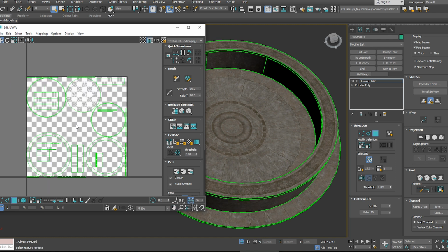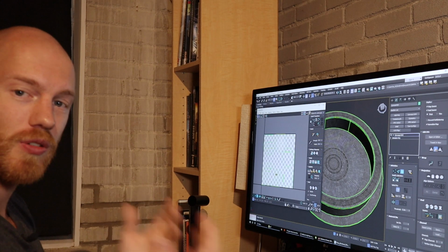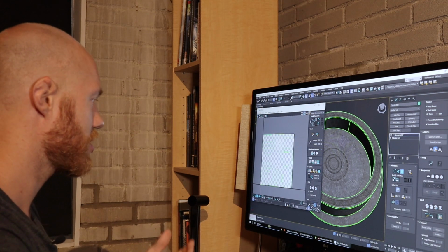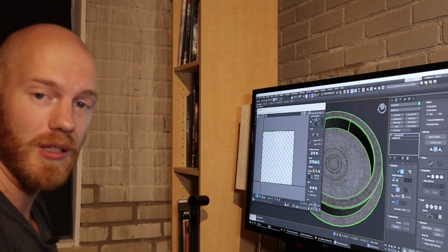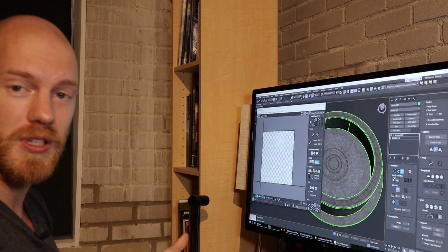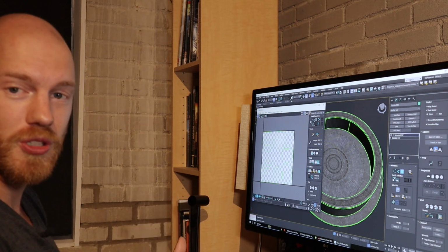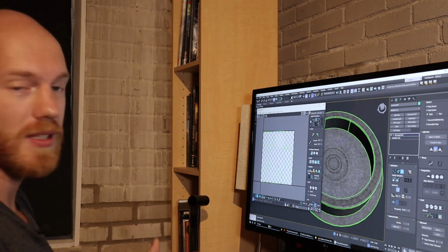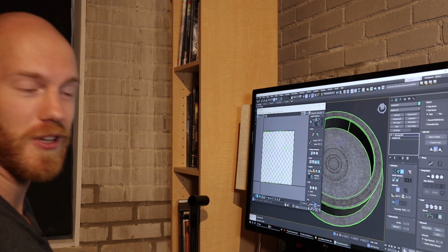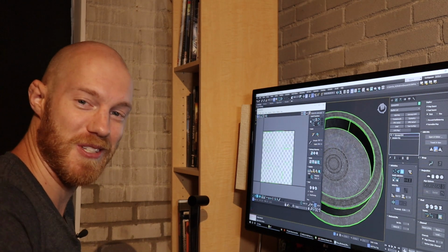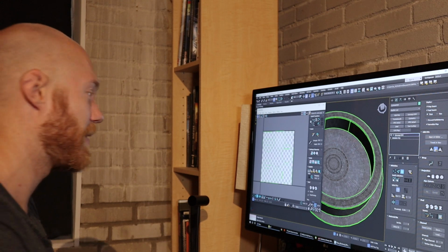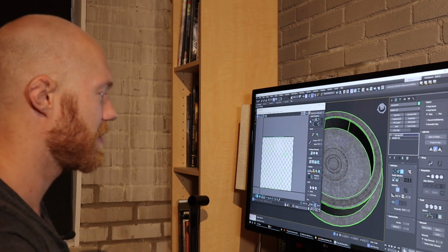Yeah, that might work for some meshes, but again, there's a ton of wasted UV space, and for our light maps, all of this is precious space that we could use to get some really nice crisp baked lighting in our textures, and allow us to use like a 24 or 32 light map resolution instead of having to crank things up to like a 512 or a 2048, which is absolutely insane and something you should never do because your bake times are going to go through the roof. So how can we optimize this a bit?